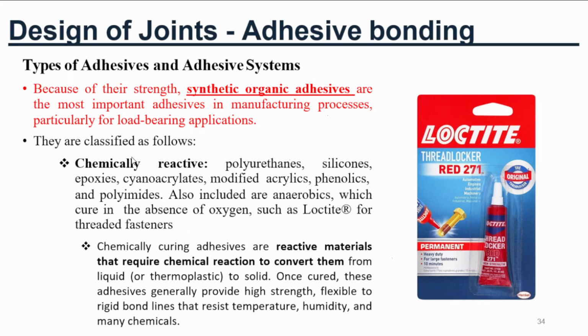Then here first one is chemical reactive adhesive. Okay, so chemical reactive adhesive includes polyurethanes, silicones, epoxies, cyanoacrylates, modified acrylics, phenolics, polyamides, anaerobics. Okay, so these adhesives cure through a chemical reactions. Okay, so liquid to solid.